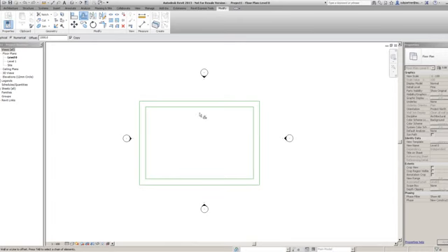Lovely. Let's see what happens on the inside. I'm going to hover over that again, left click. Fantastic. It doesn't seem to have joined it up there. It's a bit of a nuisance. It does that in Revit. Don't worry too much about it. I'm going to show you little things we can do later on to get around it. But if I keep going around, it's a little bit random. It is something I'd like to see them change, because it makes so much more sense to do it the same way as we did with the outside, where it just joins up automatically.